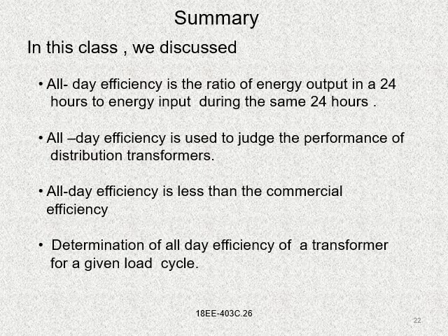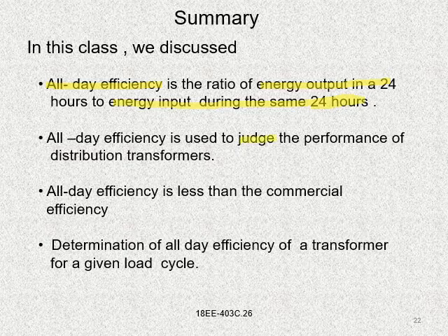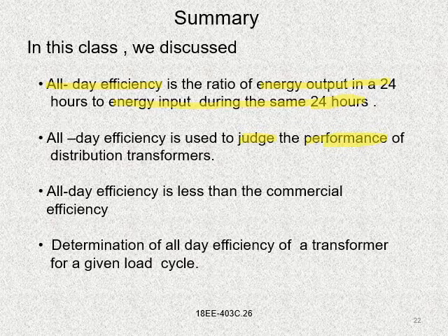All day efficiency is the ratio of energy output in 24 hours to the energy input during the same 24 hours. The all day efficiency is used to judge the performance of distribution transformers, not power transformers.